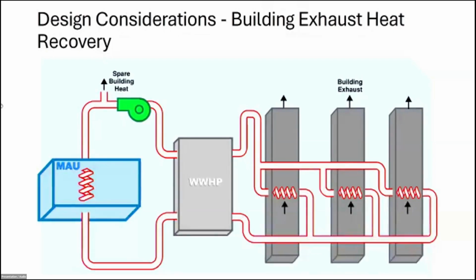And they're also at risk of putting people in hotels because on the coldest days of the year, they can't keep their domiciles at temperature. They've got about 30,000 CFM of building exhaust coming out of their kitchens and bathrooms. So they got about 30,000 coming in from a makeup air unit. That makeup air unit is not able to temper that air up to 70 degrees during the coldest parts of the year.